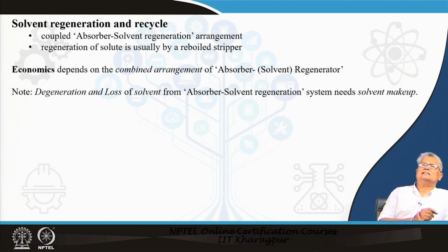This is just what I had said. You have the solvent regeneration and recycle arrangement. It is an integral part of the absorption system, where the absorber and solvent regeneration arrangement acts as a coupled system. The regeneration of the solute is usually by a reboiled stripper.